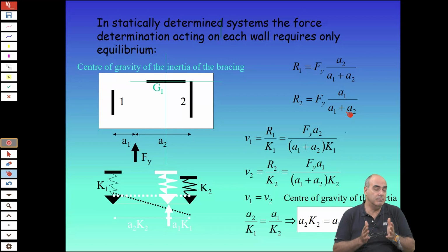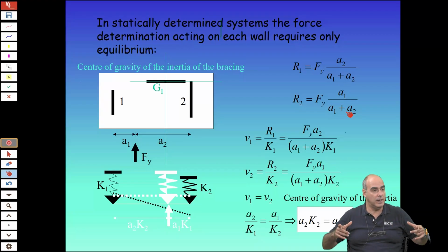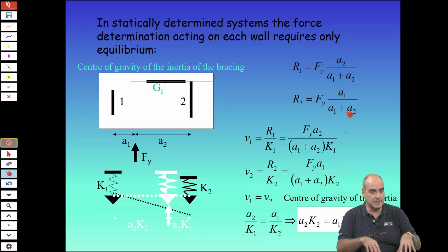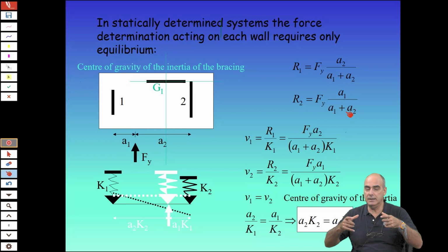And on the other hand, where the forces are applied, we have said for earthquake, we consider earthquake through a static equivalent effect. So these are inertia forces. There is the ground motion. The ground motion is transmitted to the structure, which means that the floors have an acceleration.